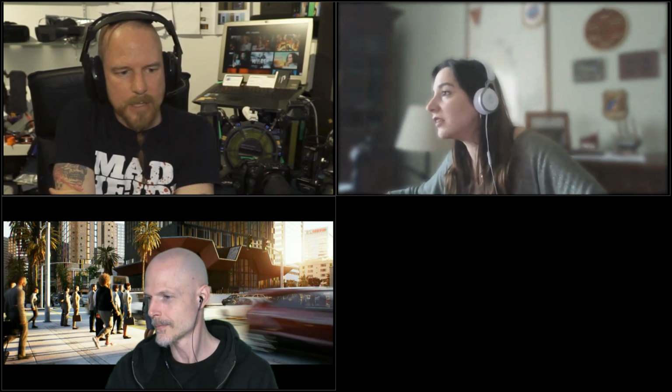I mean, especially with drones, there is the problem of glass structures. What's always best is an overcast day, so not really a high, bright sun. That's absolutely a must, especially when you do cities and everything. Sadly, you cannot always choose, because when you have a contract, you have to scan in certain days or a range. But if you have an overcast day, the reflections are not that hard.